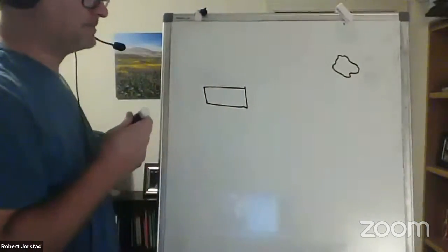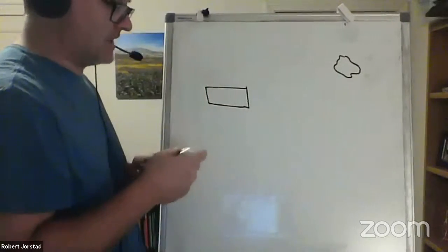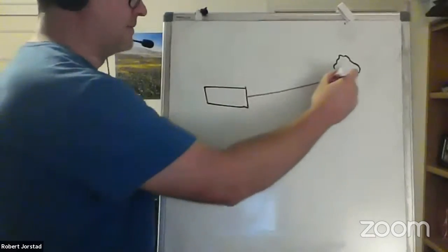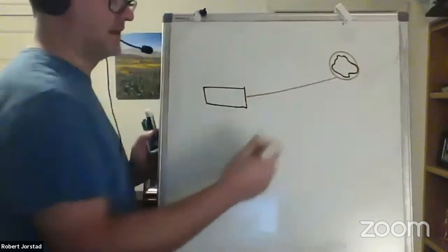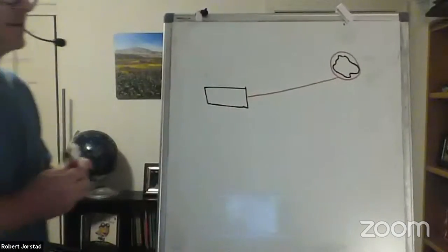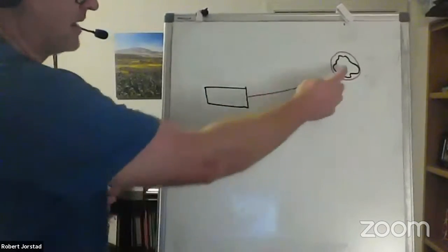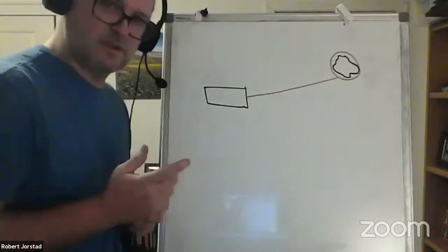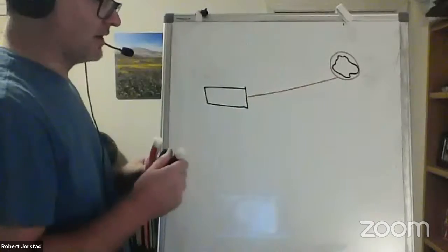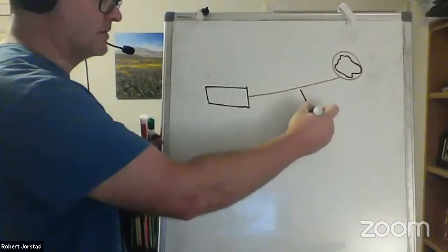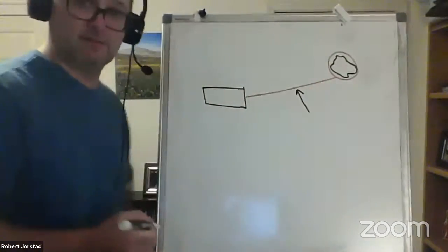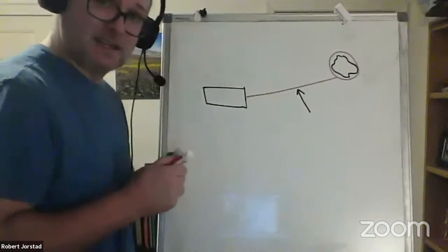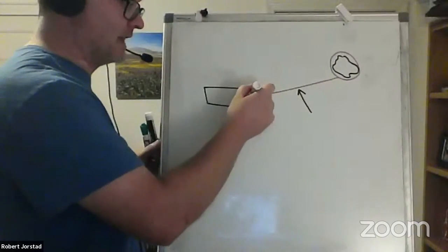You have to get kind of lucky, or a giant rock. But the idea here is you could actually tie a rope from the frame of your car, not the bumper, around the tree or rock or whatever has very large mass, an immovable object. Once you do that, you could come into here and actually apply a force perpendicular to the center of the rope. And when you do that, you basically get a force multiplier. This is effectively a lever.